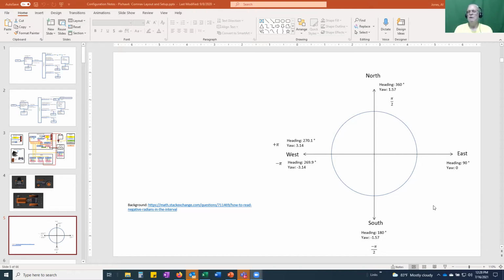Anyway, I was playing with that gps_heading.py, and it subscribes to the velocity message, which is an XY speed vector. By taking the arctangent of X over Y, you can extract the heading back out of that, either in radians or degrees.